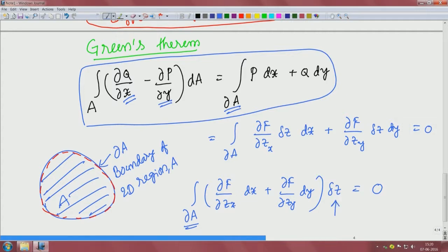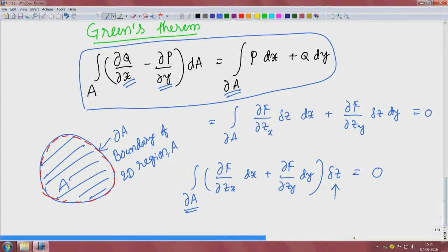That is what we call the essential boundary condition, meaning z is specified. If we go back to the plate problem, if w(x,y) is our function and the plate is clamped around the edge, there δw, that is a variation of w, just like δz, will be 0. So, then you are fine.